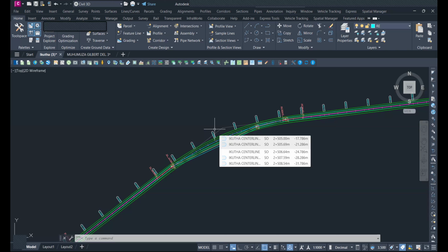So that is one scenario where we do widening for that case. This means it's from the road survey that was done, and it has informed you. And this is, for example, something that will happen a lot in your area of jurisdiction because you're dealing with very, very large tracts. And in such a case, you can be able to do widening, that is, if the radius is very close to the minimum radius.